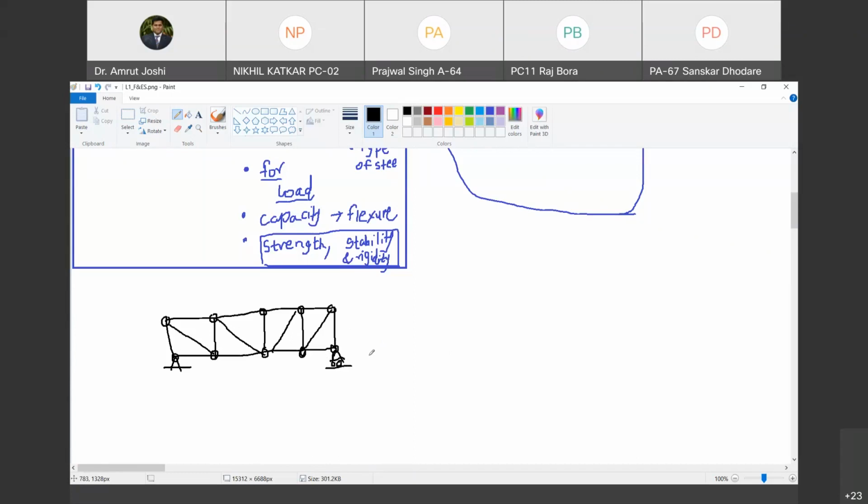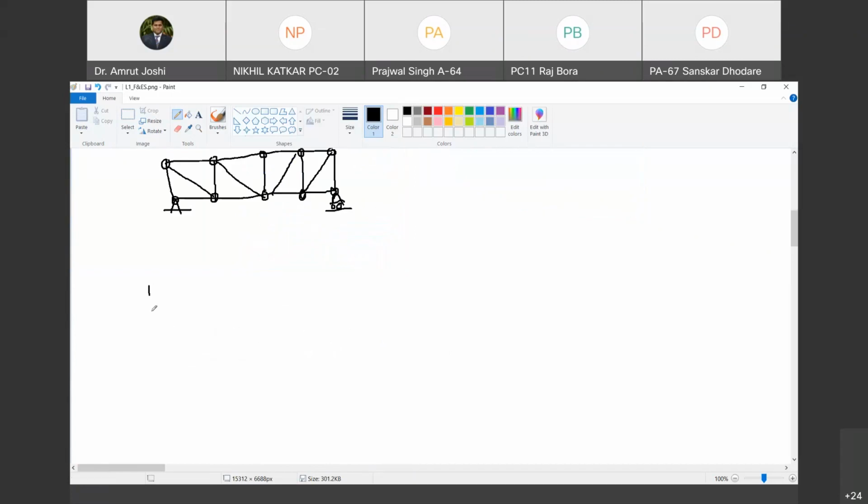Yes, sir. Okay. Let me give you another example. You will find this example which has already taken place, a case study of a building in Japan, where after the earthquake had occurred, the soil went into liquefaction and the foundation lost its stability. The entire building did sink by an amount equal to the height of one story. There was no single crack anywhere in the building, not on any beam, not on any column. There was no structural damage, but the structure lost its stability.